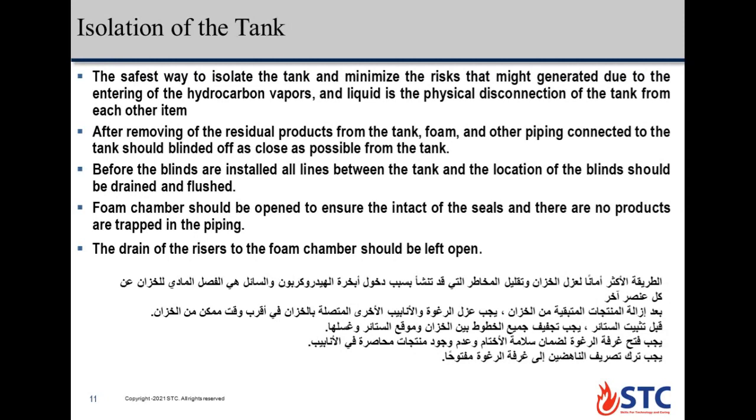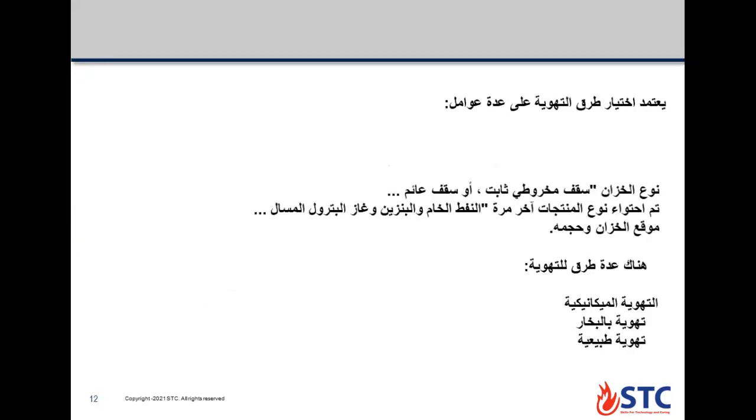Before the blinds are installed, all lines between the tank and the location of the blind should be drained and flushed. Foam chamber should be opened to ensure the integrity of seals and that no products are trapped in the pipe. The drain of the risers to the foam chamber should be left open.